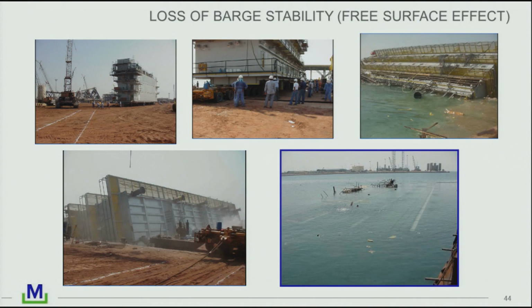Barge has got to this point, free surface effects have taken over, whack, over it goes. Any normal stability software we can take that into account. You don't need software, you just need to do the hand calcs to do this. Yeah, and in fact that's the case with all these ships that have turned over, capsized because of free surface effects.